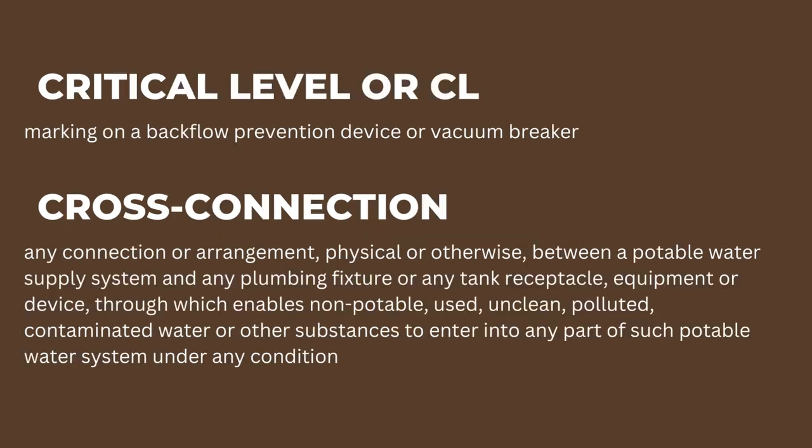Cross connection: any connection or arrangement, physical or otherwise, between a potable water supply system and any plumbing fixture or any tank, receptacle, equipment or device, which enables non-potable, used, unclean, polluted, contaminated water or other substances to enter into any part of such potable water system under any condition.